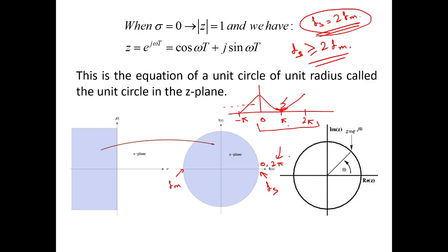When high frequency components get mixed up with the low frequency components when it is repeating, at this point there would be mixing up of the high frequency component of the original signal with the low frequency component of the repeating signal. Then the thing is called aliasing.